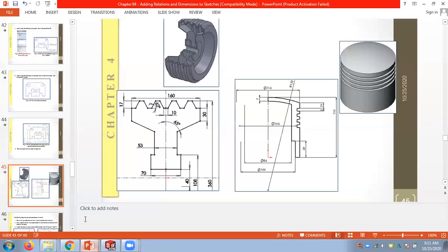So in this drawing, there is no problem. Contour line is here, center line is here. So you can easily apply a thickness to the drawing, and inside will be hollow. So we can apply a 10 millimeter thickness to the drawing. So there will be no material inside. Otherwise, there will be full of material here if you apply a solid revolve. So just do it and see, any questions, let me know. I will also have a simple sketch for this and show you how thin revolve works.